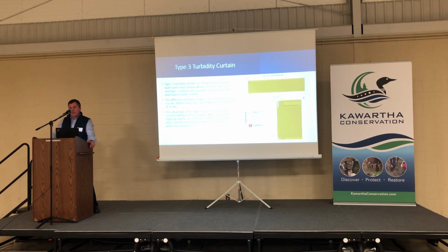And then the second last curtain that I'm going to talk about here, a little bit to do with the Type 3 curtain. These are typically used in higher flow applications, tidal applications. It does have a fabric permeable body in most cases, and it allows the water to be able to move in and out. There's also the impermeable version available, and we can install these in depths up to 30 meters deep. So these are considerable curtains, really heavy duty. They provide a lot of heavy lifting for these types of installations.